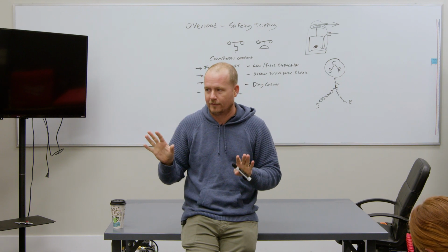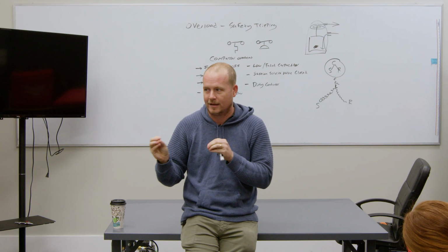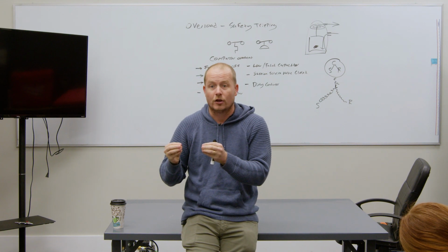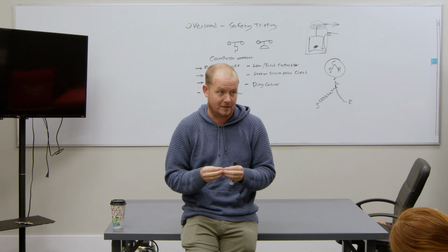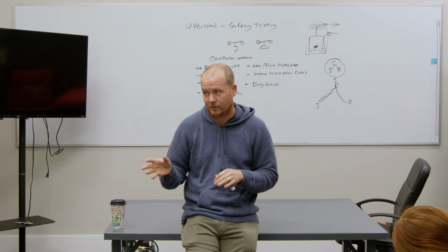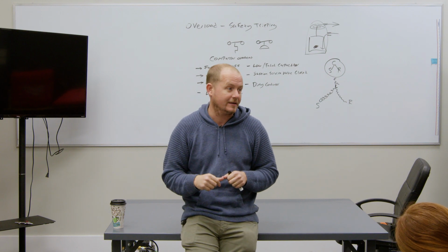Now, I want to be really careful about what I'm about to say here, because I'm not saying to jump things out and leave them that way, and I'm not saying to do anything unsafe. But what I am going to say is, go ahead and jump it out so that you can figure out what caused it to fail in the first place. Do it safely. With gas, you would have to be really careful. Like, don't jump out a rollout switch, because I don't want it to roll out in your face.